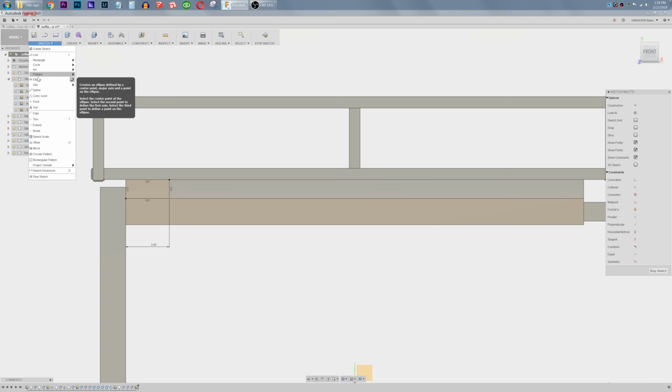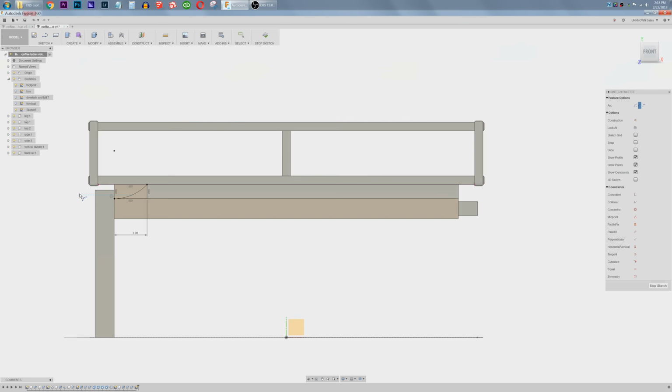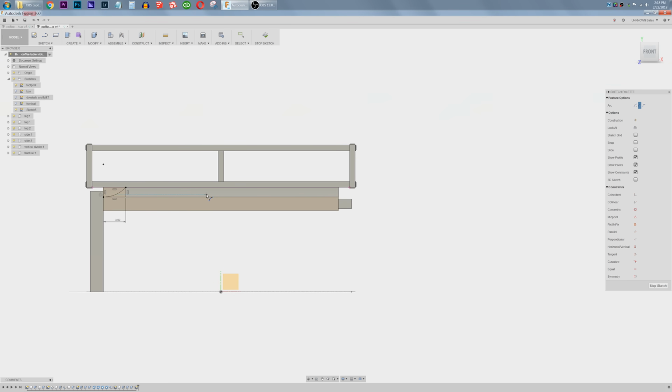And we're going to sketch an arc. I always want to say A for arc, but in this program, it's appearance, not arc. So from here to here's my arc, and I'm going to bring it down to this line so it's tangent on this bottom edge. Never draw what you can copy, so L for line to create a construction line based upon the center point of this rail.